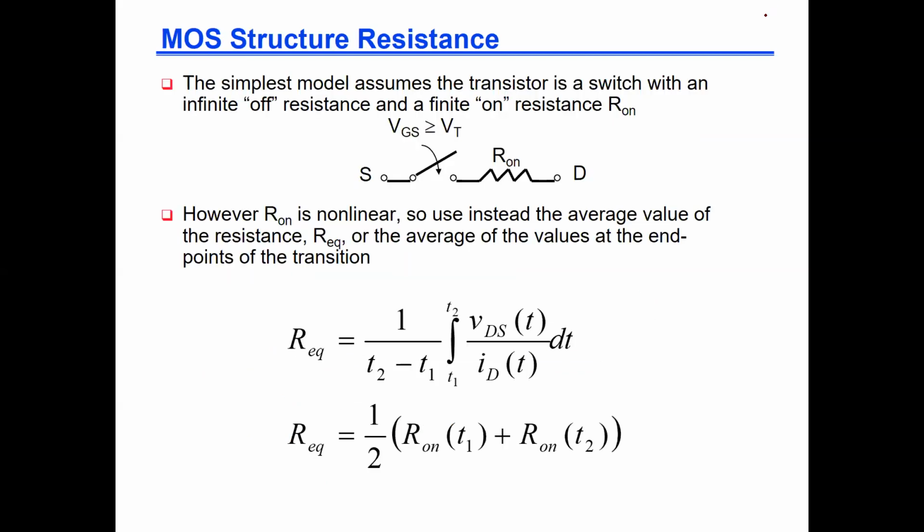If I want to model my transistor as a resistor, really when VGS is greater than VT, I will have R on come in place. Otherwise, if the switch is off, I have an infinite resistor, it's a pure open circuit. To model this R on, typically the transistor is a resistor between the drain and the source, or a current source between the drain and the source.